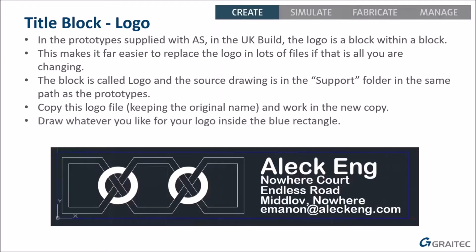And then inside the new logo, you can do anything you like. The blue rectangle, if you're keeping with the existing title blocks and you're only changing the logo, the blue rectangle is the limit of the size you can use. So delete everything inside the blue rectangle and draw your own new logo inside the blue rectangle. Put in whatever text and whatever you want in there.